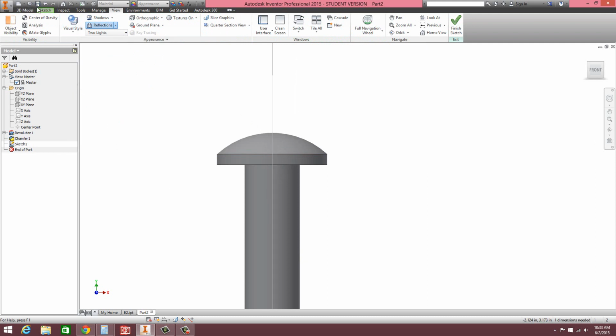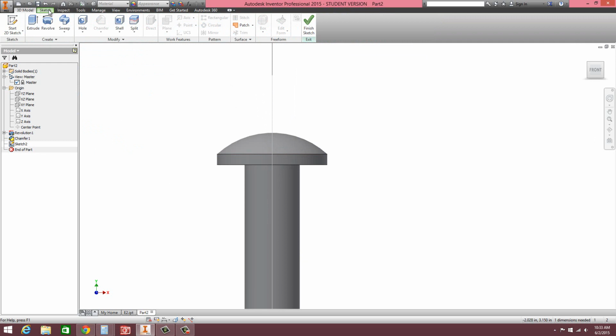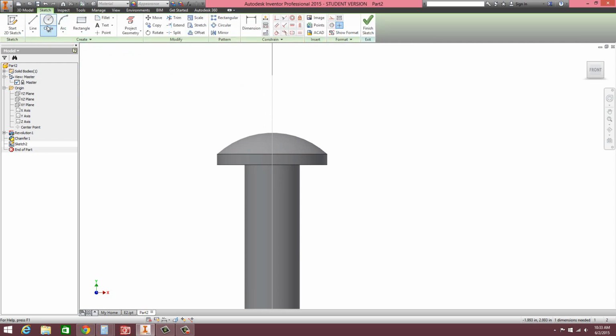Okay, go back to 3D sketch, and we're going to go ahead and take the line tool, and you're going to draw a little line across like that. Dig into it. So essentially we're making the tool to cut that out. Then hit escape. And we're going to go ahead and mirror that across. So again, go to the mirror tool. Select is already selected for us. We just click and drag a fence to surround what we want to mirror. Click on the mirror line, and that vertical center line we created should go ahead and apply that then.